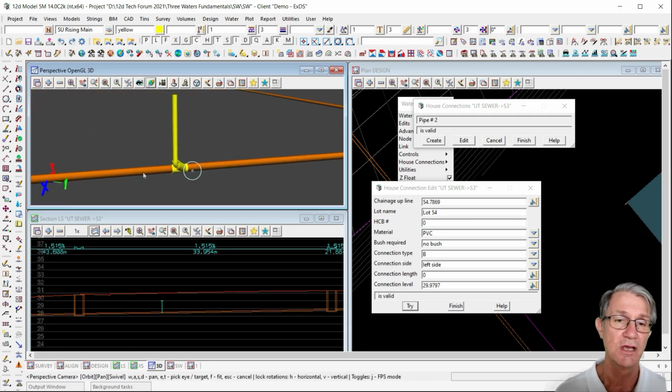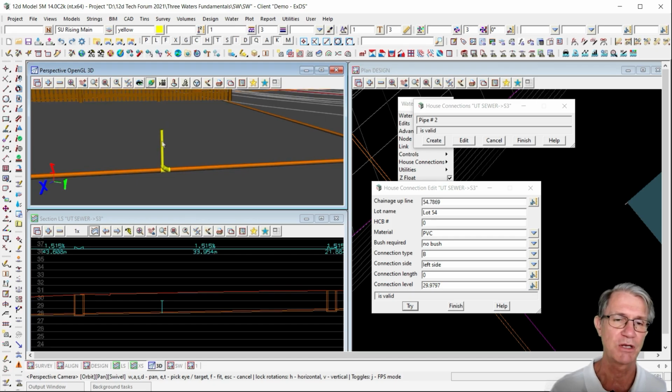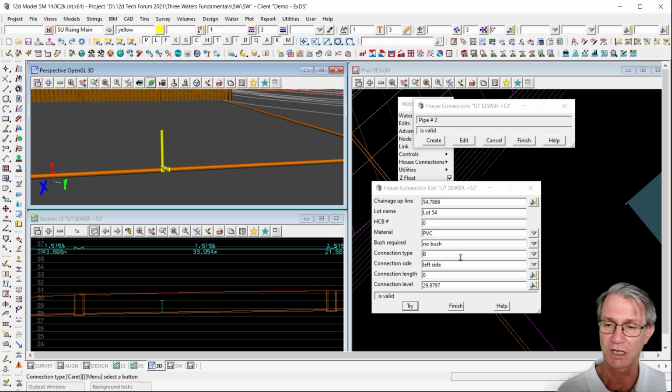As you can see. Now if the plumber wanted to come in at the top of there, that's fine. If they wanted to come in deeper, cut off that riser and join in partway down, that would be fine as well. But the infrastructure that's left when the sewer is built is this riser coming up to 1 meter below the surface.